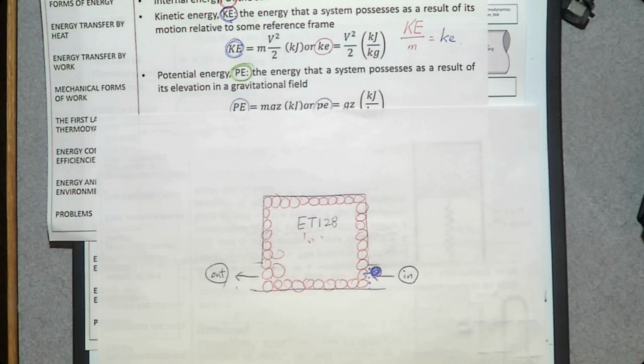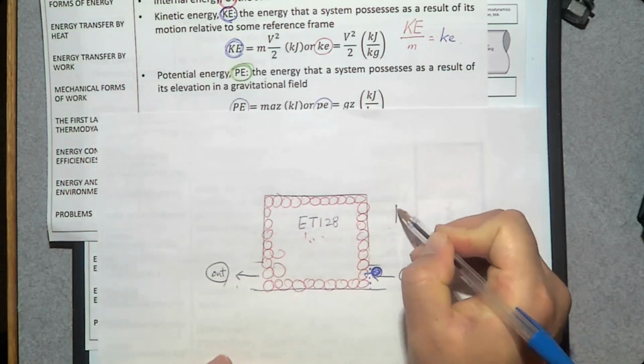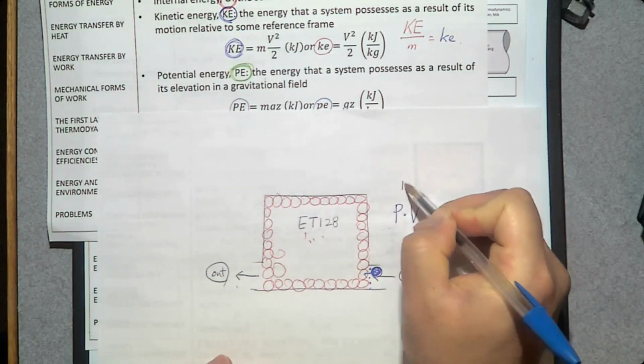To do so, I need to provide energy into this control volume. What kind of energy? What I just did. Yeah, mechanical energy. So how do you determine that? I push someone, right? And that is pressure to create volume. So pressure times volume is the energy that I provided into this room so I can walk in, right? So that is pressure times volume. That is flow energy.